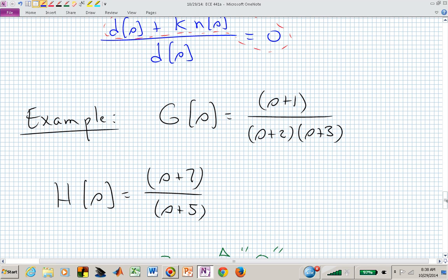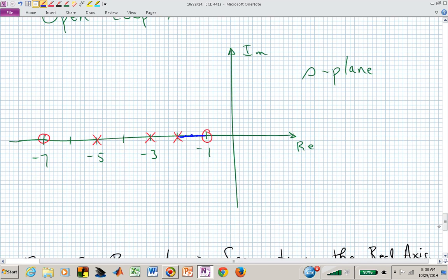If I now look at the angle contributed by that 0, what's it contributing at this point? If I said, I'm right there and I want to know that 0, what's the angle of that 0? It's -180, because I have to actually look around and go that far to get to that point. I have to turn 180 degrees to get to that point.